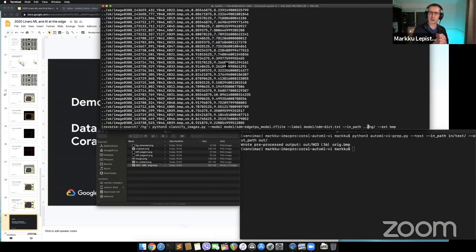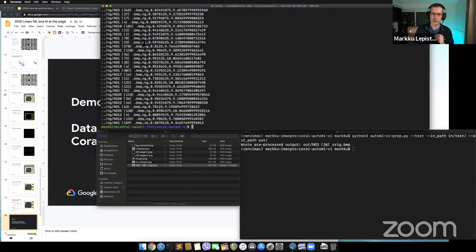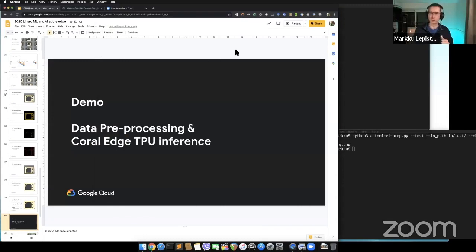Next, very quickly, let's run the same model against all the known to be bad components, broken components. So now you can see that in most cases, the model is saying not good, not good, not good. So that's correct. They are not good, but actually the last example was again a mistake. The model said that, yeah, that's a good component when we know it's not, but again, the confidence was low at only 50%. So that was an actual test of the Kyocera manufacturing visual inspection model against both good and bad objects. And you can see that in most cases, the machine learning model was correct in 95 to 98% of the times.